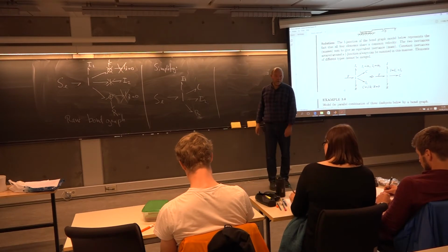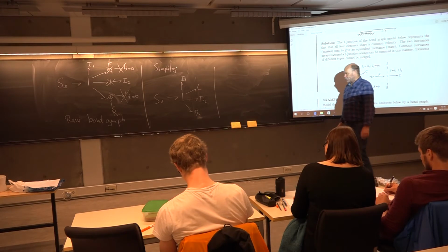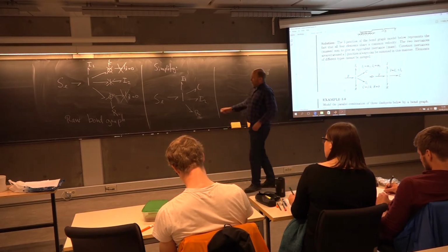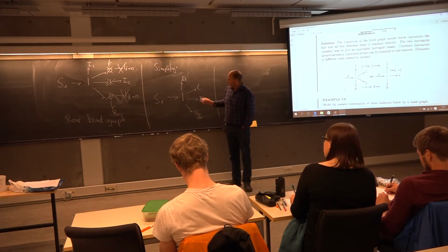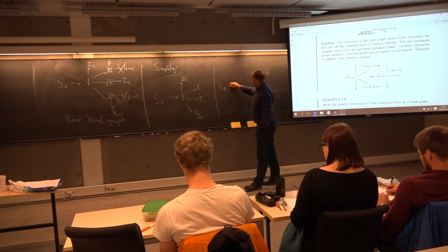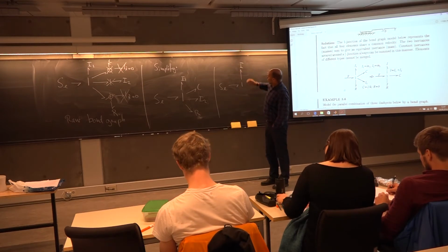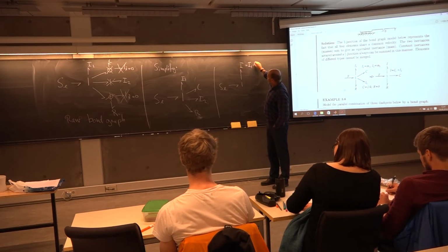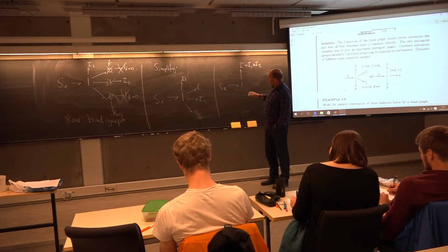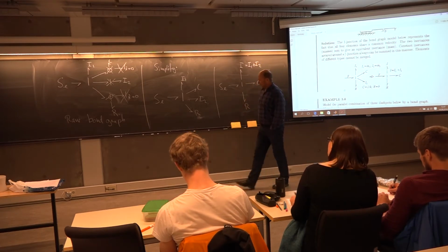And now another simplification. We have two masses attached to the same one junction. Of course, we can just join these two masses together. So the final version will now be a total mass, which is the sum I1 plus I2, a C element and an R element.